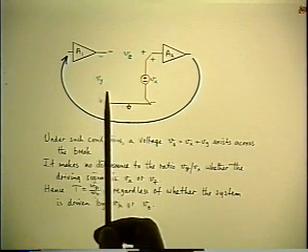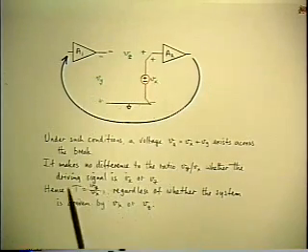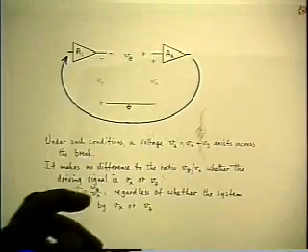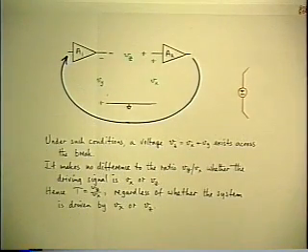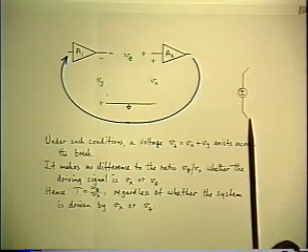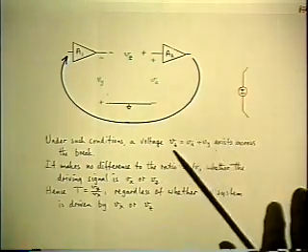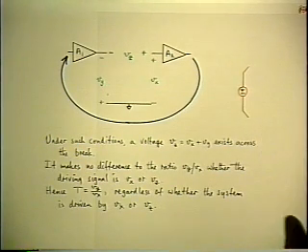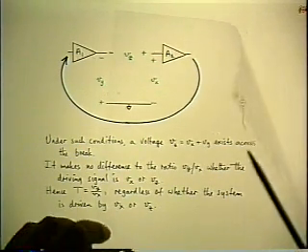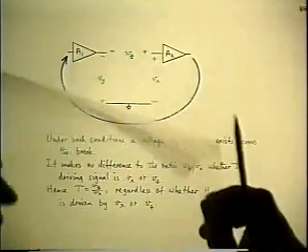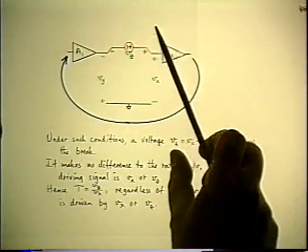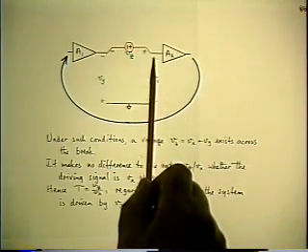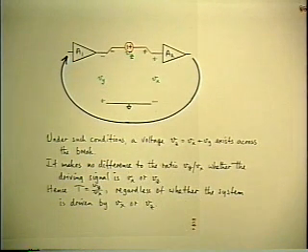Okay, now remember the answer that we looked for is Vy over Vx, which is 10. Now, I'm going to do something different. I'm going to take my signal generator away, and put the voltmeter across it, and crank up the knob on the signal generator until it reads 11 millivolts. And then I'm going to take the signal generator, which is ideally floating and all that, and connect it across the gap, still set to 11 millivolts. And I take the voltmeter and I hang it across Vx. What does it read?